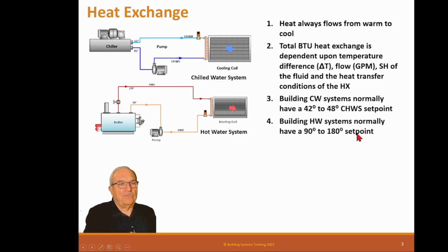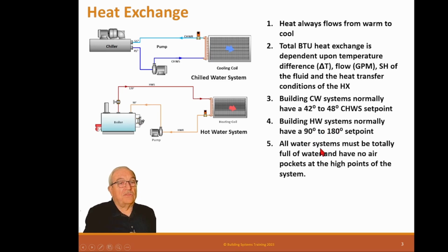Building hot water systems are normally 90 to 180. You can go lower than 90, but that doesn't provide much heat. We don't go much higher than 180 because of getting too close to 212, and we don't want to cause anything to get close to steam.